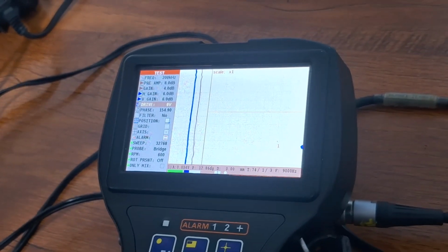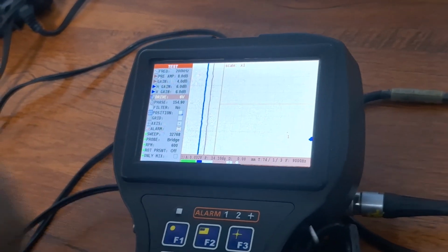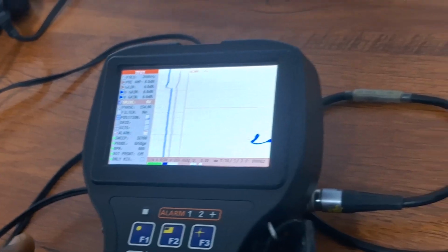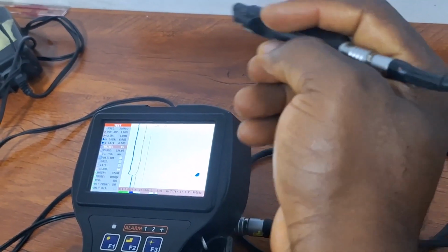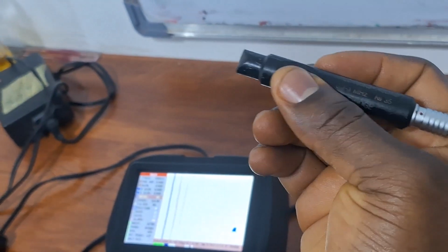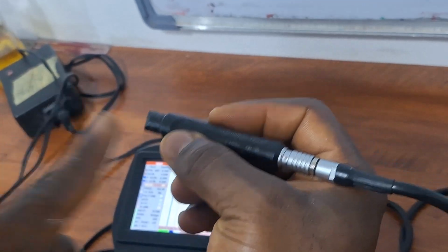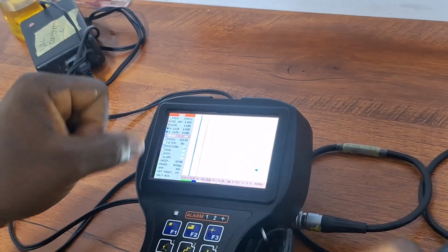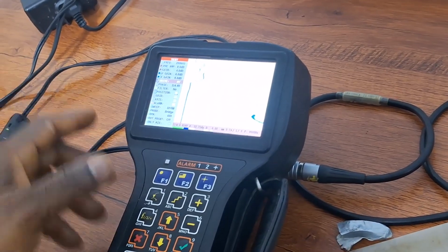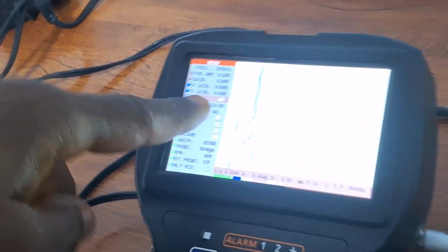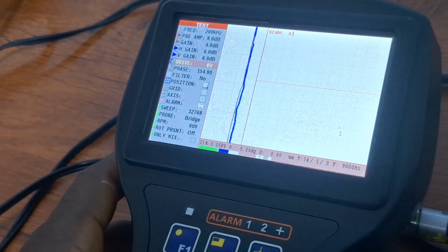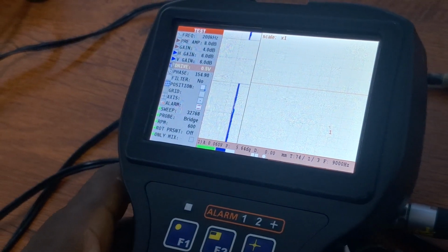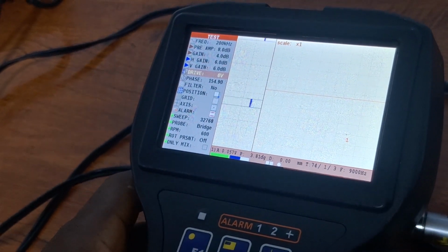It's a force. Let me use the word force. It's a force that will be driving the electrical current that is coming into the coil, which means the higher the voltage, the higher the force that is driving the current, which will ultimately affect how your impedance curve comes. My advice is do not over increase. We have the maximum of 6, so stay away from 6.